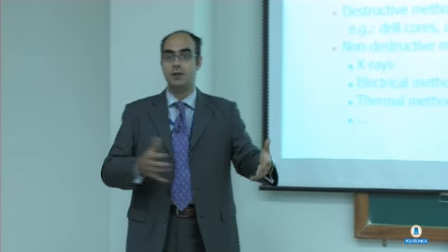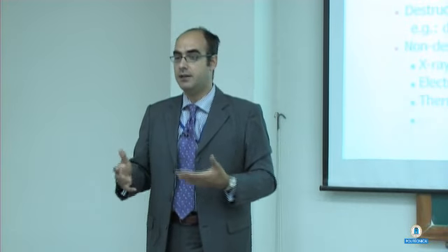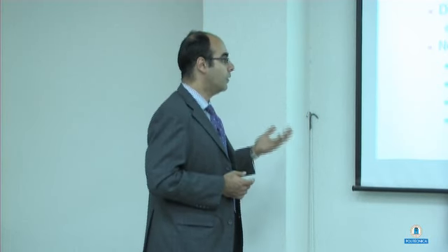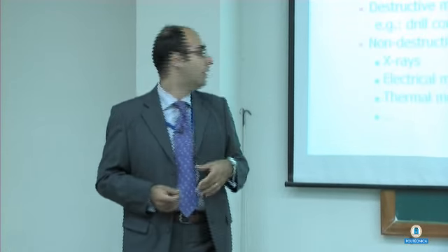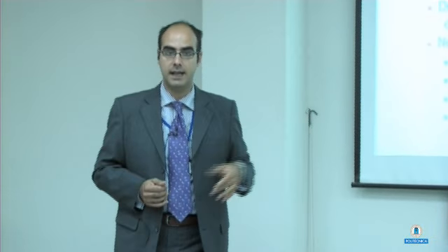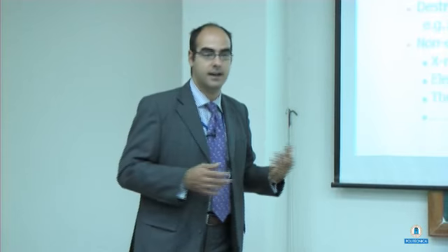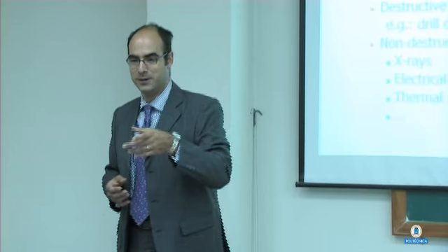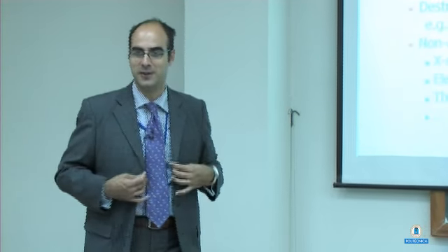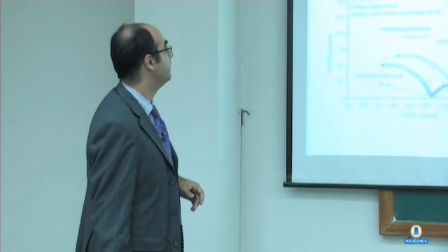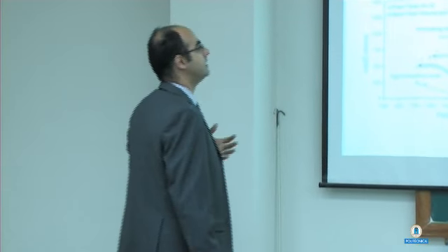X-rays can be good, but you need the equipment, and there are also some safety and health issues, because there are radiations. So we have worked and we are currently working on electrical methods, and also trying to see if thermal methods can be effective. I have some friends working on this subject, and we were speaking together before. Roberto Felicetti is working on that because he's an expert. But I will tell you about electrical methods basically. The method is called alternate current impedance spectroscopy.